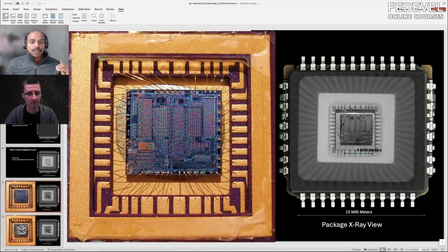Now, if you're designing a chip targeted for high performance, the simple example is what we call the SerDes, serial connections. They run at a very high frequency in gigahertz. It starts all the way from 10 gig, then 30 gig, 64 gig, 112 gig, 256 gig.